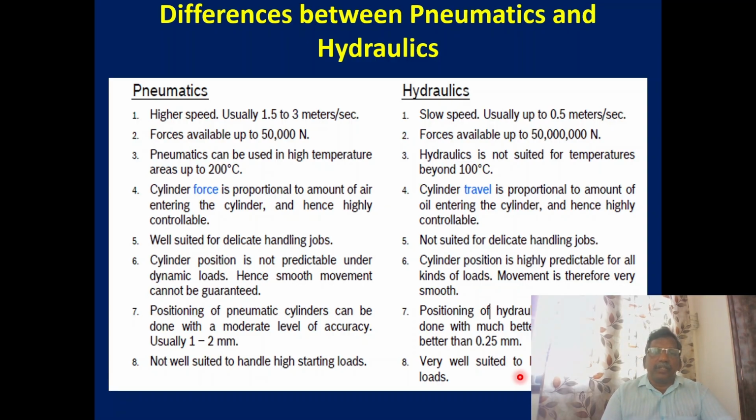In pneumatics, cylinder force is proportional to the amount of air entering the cylinder. In hydraulics, it is highly controllable, as the cylinder travel is proportional to the amount of oil entering the cylinder. Pneumatic systems are not suited for delicate handling jobs. Cylinder position is not predictable under dynamic loads, but in a hydraulic system it is predictable under all kinds of loads, and therefore very smooth. You can't expect that smooth movement in a pneumatic system.